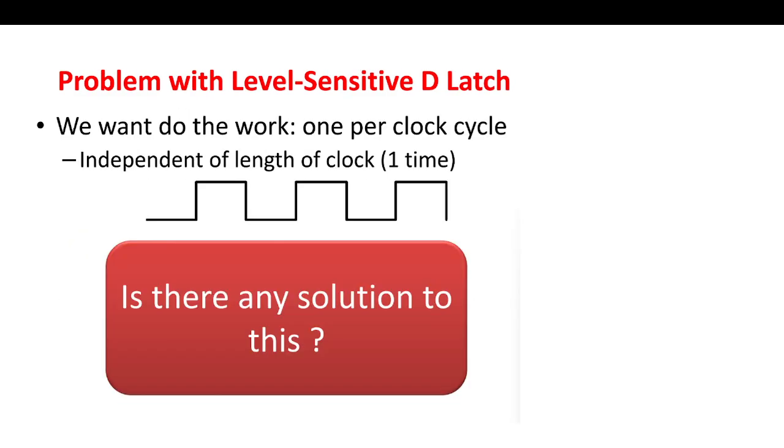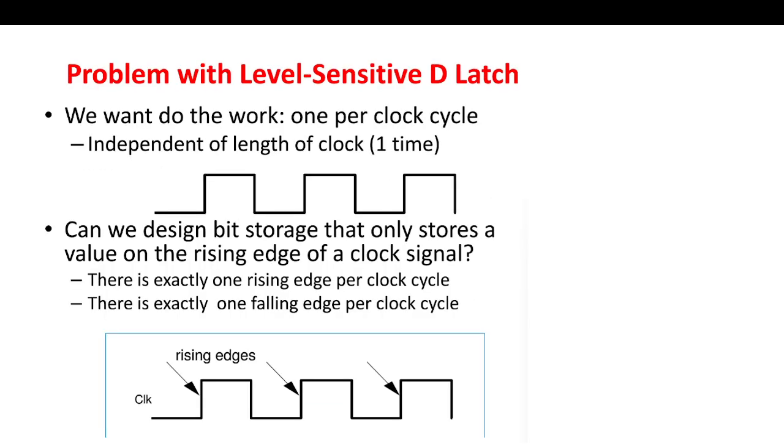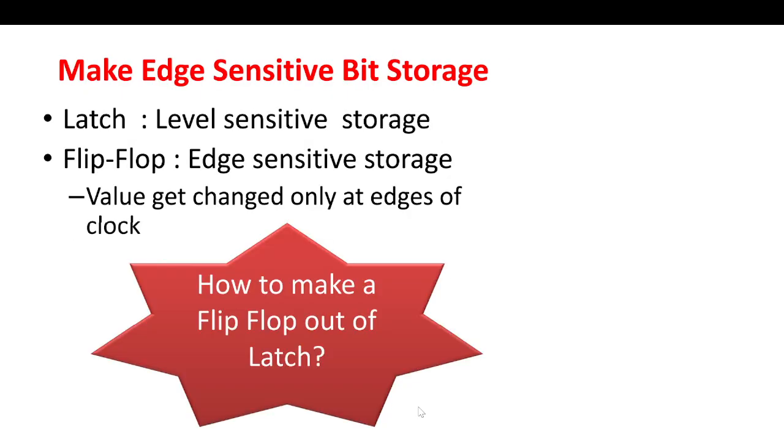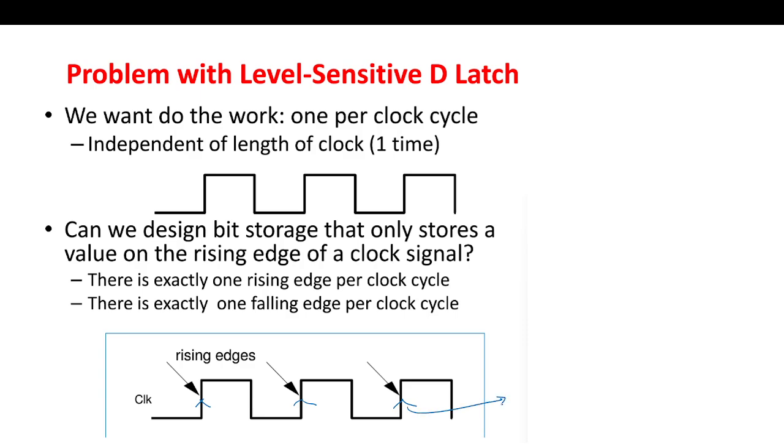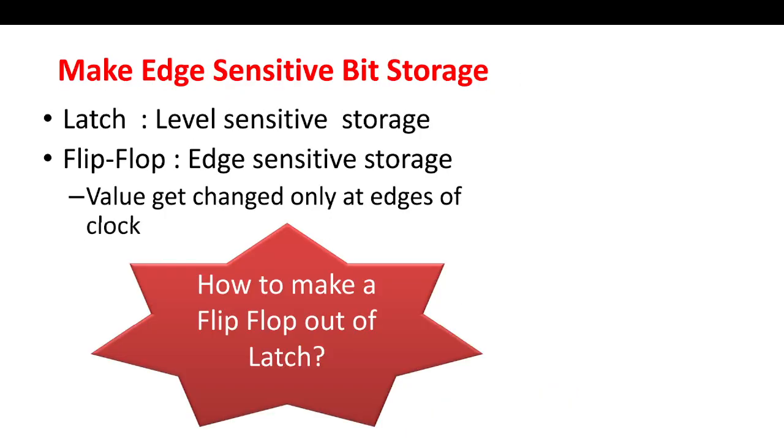So that is called an edge triggered circuit, and that is called the flip flop. If it is a rising edge, in Verilog we will call this rising edge posedge. Generally, latches are level sensitive storage devices and flip flops are edge sensitive storage devices.